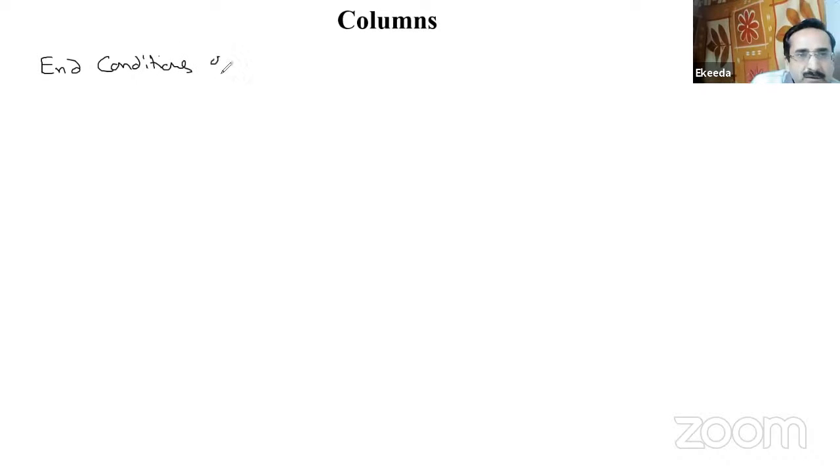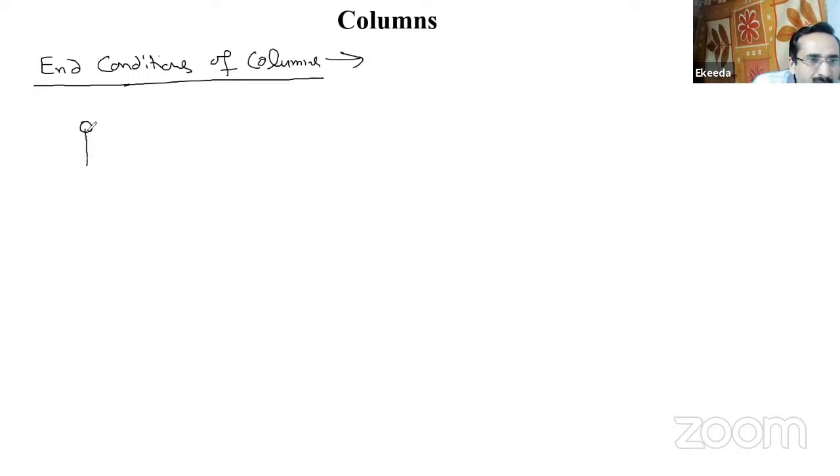The first possibility is that the column on which the compressive load is applied has a hinge joint at both sides. Most of the long columns are assumed to be hinge joints. But the columns which are connected to concrete structures are assumed to be fixed columns.